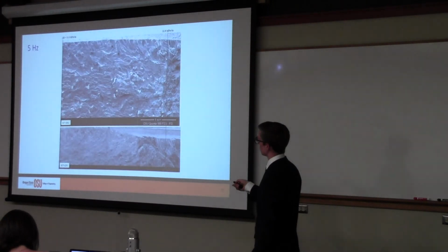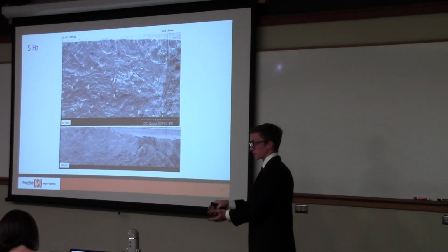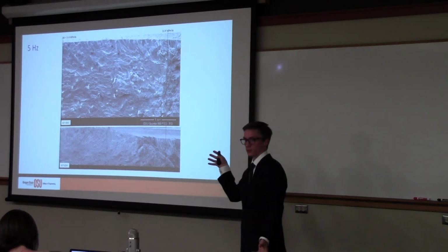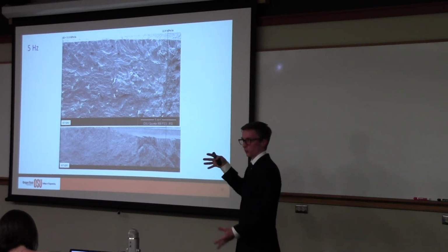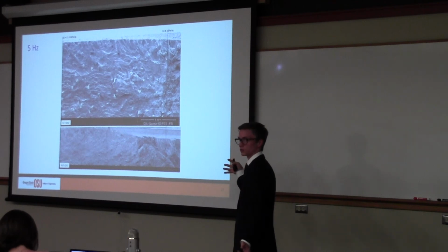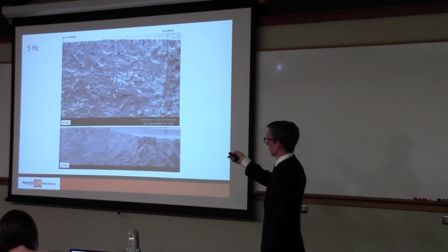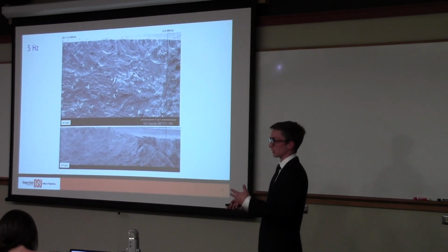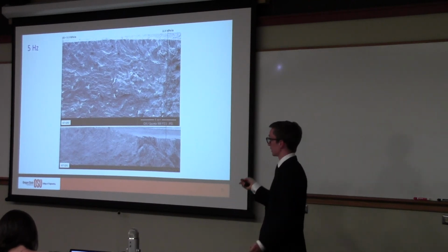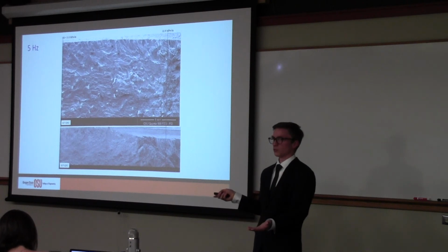That's why we see less roughness at the end. The roughness is that branching behavior that we saw in the profile. So the mechanism change is visible on the fracture surfaces at the higher frequencies, but it doesn't translate fully to a higher crack growth rate because it's not allowed to happen. The crack is growing too fast.